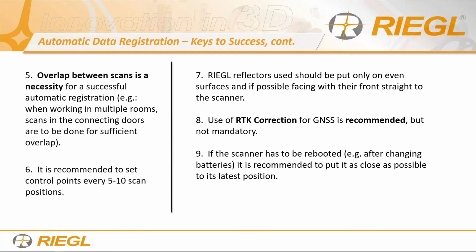And if the scanner has to be rebooted, since a lot of projects are large, or you're taking a break throughout the day, it's okay. You don't have to worry that you didn't finish the whole project in one day. But if you do have to reboot to change out the battery, or take a lunch break, or the project consists of 5 days, you want to make sure you start where you left off, as close as possible, if not right on the same spot. That way the registration will continue to pick up with sufficient overlap so that the next position after that will also tie in very well. So, don't just jump all over the place.